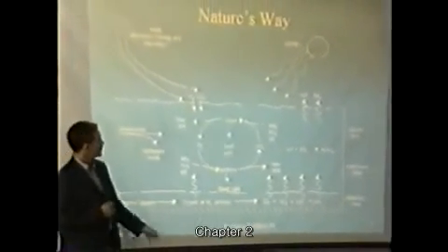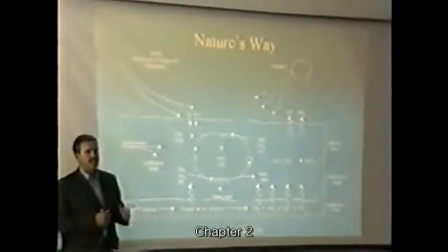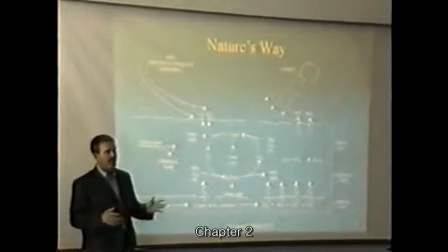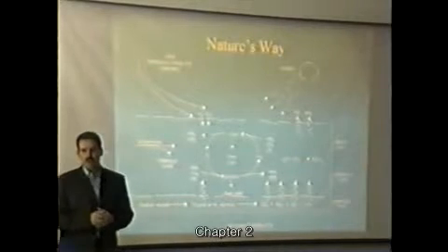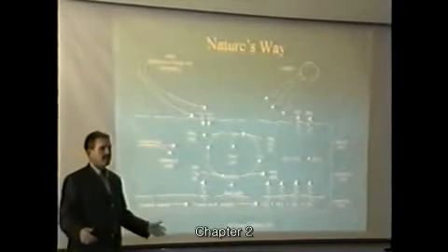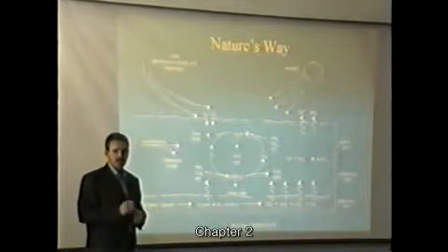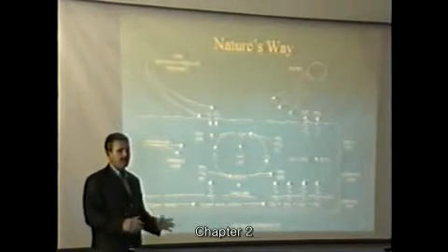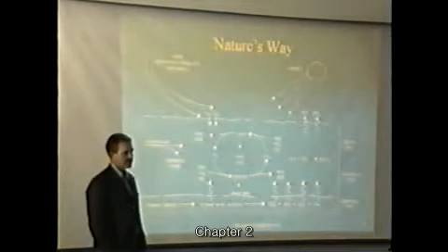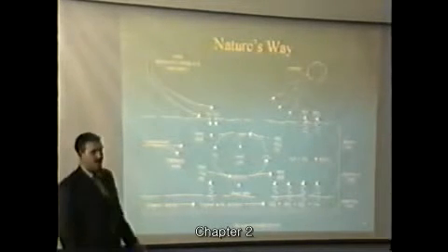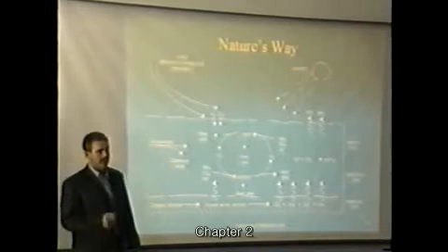You have sunlight, you have wind introducing oxygen and CO2, and this system is in balance. In our country, South Africa, we have lots of oxidation pond systems, and if they are designed properly and correctly, on correct loadings, they will function properly for years, even 100 years, without a problem.